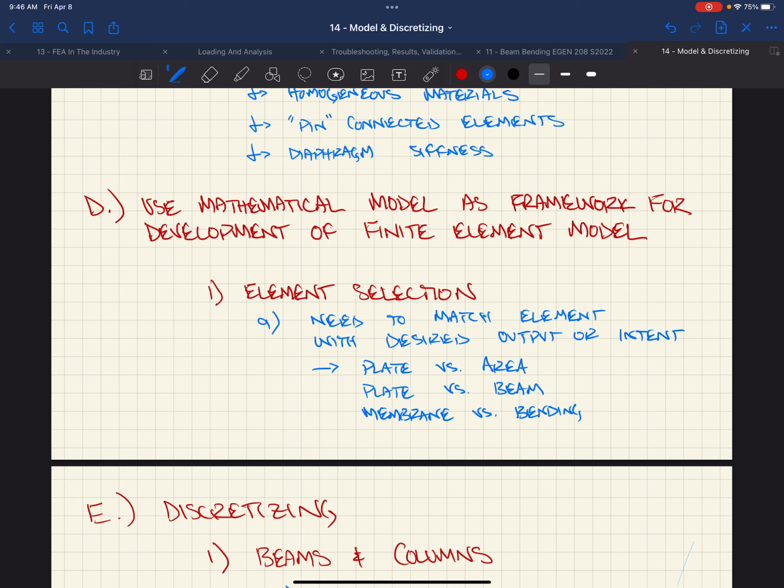If I'm doing a time history analysis on Norm Asbjornsen Hall, right, I'm going to hit it with an earthquake. The out-of-plane bending of the diaphragm probably adds quite a bit of stiffness in some aspects of that building's performance and behavior that I would want to capture if I was shaking it with El Centro, right? If I was shaking it with the Hebgen Lake earthquake, right?